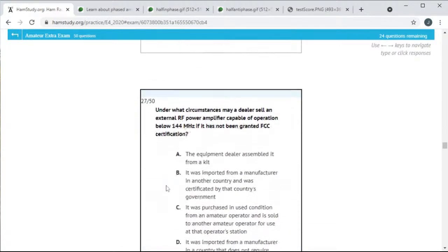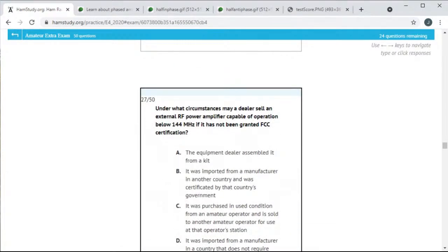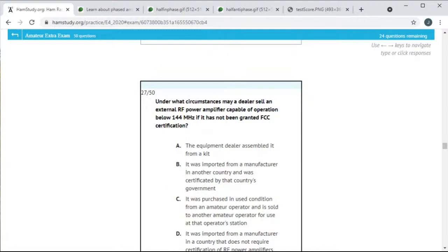The gain of an omnidirectional antenna, like a 5/8 wave antenna, is taken by squishing the field so that more of the power goes at what people think is a preferred takeoff angle. So not as much is going directly into the sky.